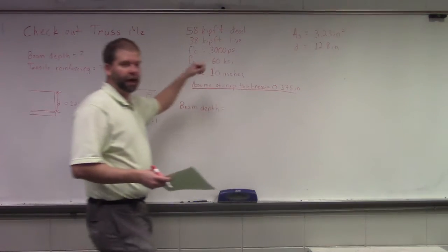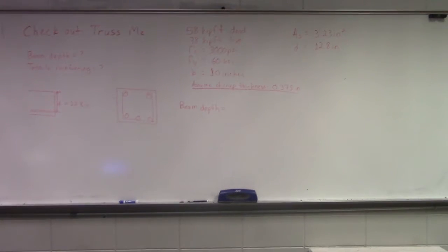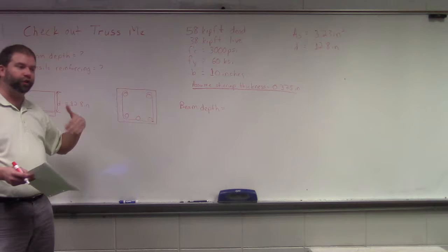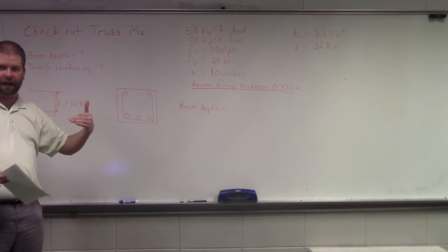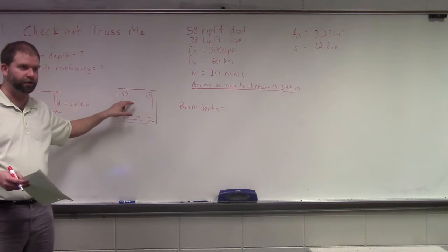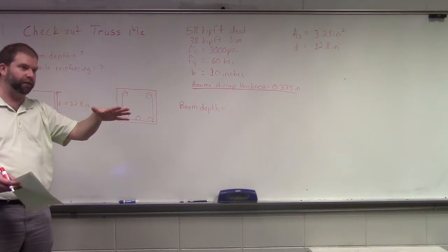What John is asking about is that oftentimes in beams, there's going to be steel at the bottom, and also steel at the top. So the first step is determining how much steel in your tensile face. Once we get through that, I don't think we're going to have time to look at determining the amount of steel that we put in the compression face, but it is something to be aware of.